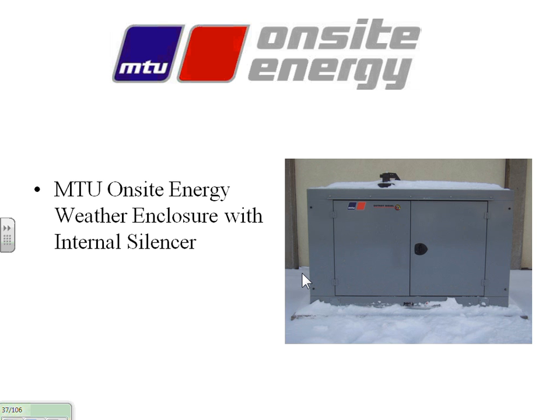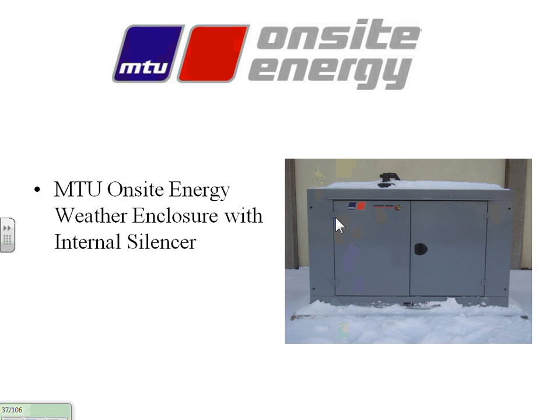So what they have is a pusher type fan. And in a situation like this housing that we have here, we'll say the radiator is sitting right in this area here. It's going to push air out this way, which is going to create a negative pressure within the enclosure and draw air in through this side. So a little different technology, same stuff, but instead of sucking the air in, it's pushing it out.